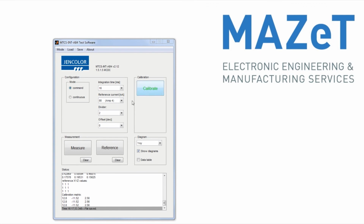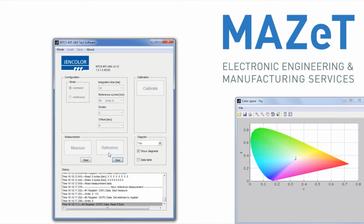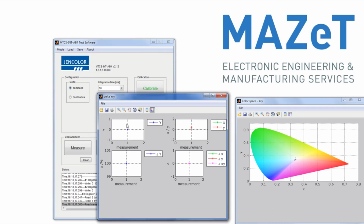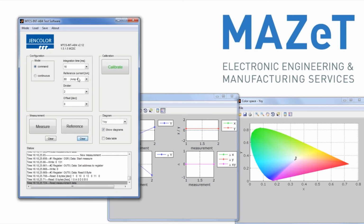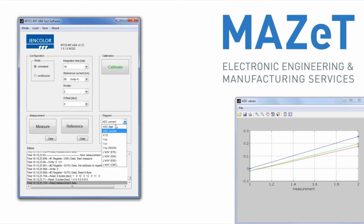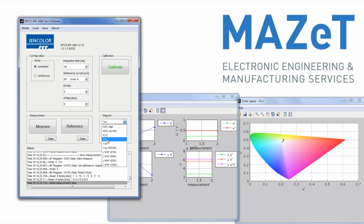With an application-calibrated device, it is possible to measure values and compare them to reference measurements. You can freely choose your diagram type to show what color or ADC values have been measured. The reference measurements allow to determine the delta margin between two color points or measurements. Therefore, accuracy comparisons are possible. There are several diagram types to choose from. Keep in mind that the MTCS-INT-AB4 does not have an included illumination source. Therefore, it is ideal for self-illuminated objects such as LED systems, monitors, or other displays.